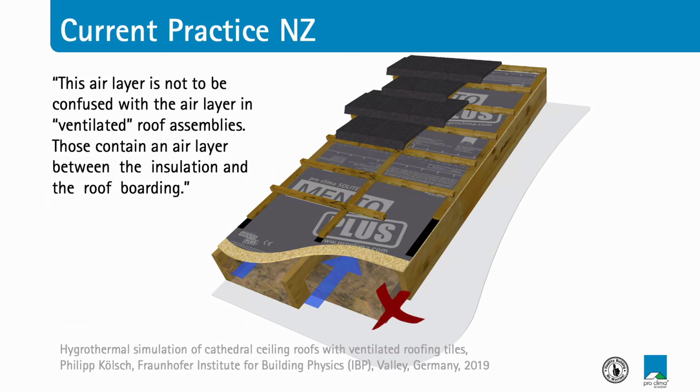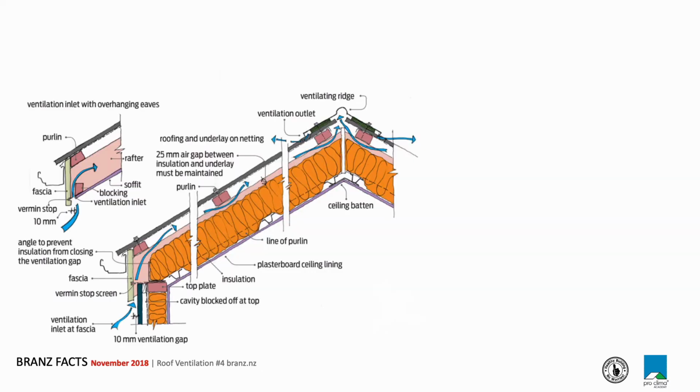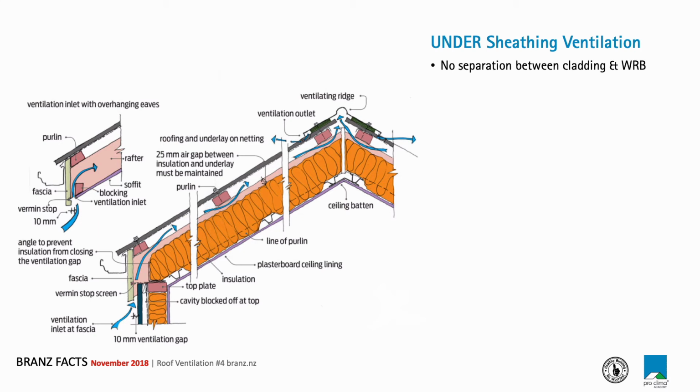This is not the ideal situation because that air movement doesn't contribute much, or anything, to the cooling of the roof, and it also doesn't necessarily help dry the roof assembly out where we want it. But it's the way that we have been doing things, and it's the way that we've talked about roof ventilation. But the air movement in this location has some problems.